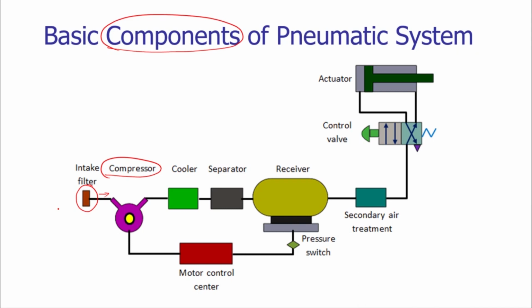As we have seen by Boyle's law, when the volume is reduced and pressure is increased, the temperature will also increase. So we need to reduce the temperature of that pressurized air. Once it is reduced to the normal temperature, there may be condensation of water particles inside that pressurized air. Whatever percentage of water is inside the air will get condensed when we reduce the temperature, when we get it to the normal ambient temperature.